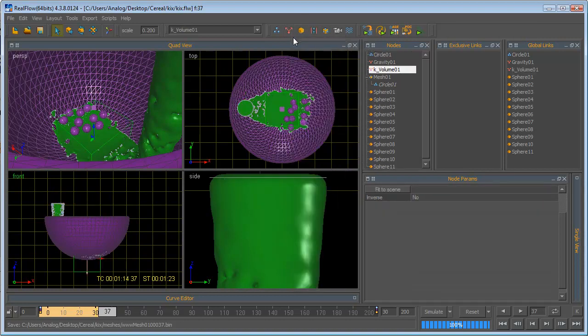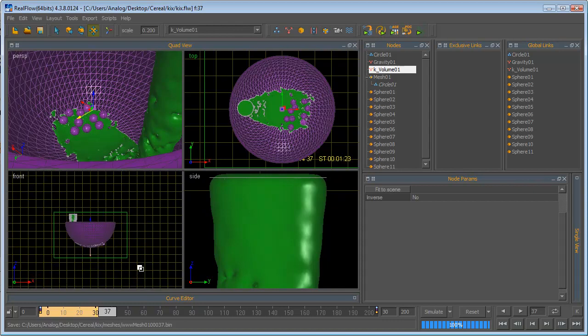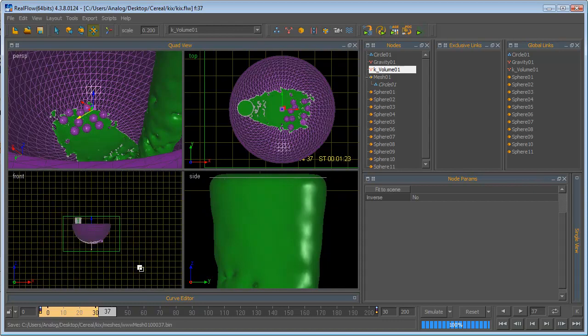Just go down to Daemons, Volume, and throw it around like your work area. Go to Scale here, and it'll get rid of any particles that happen to fly out of the emitter that you don't want. So say my cereal bowl puts some liquid on top that goes over the lip of the bowl. It'll fall to here, and then boom, once it hits this, it disappears, which is good to know because you don't want random liquid flying all over the place.